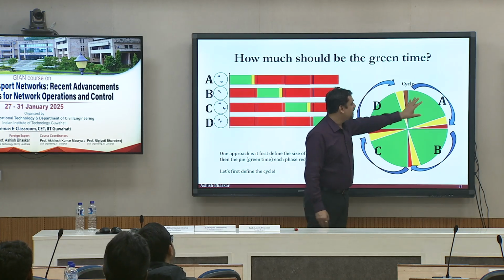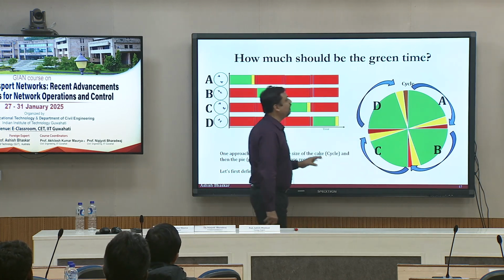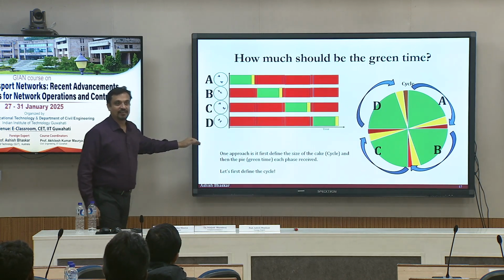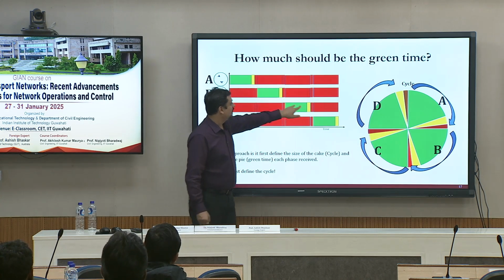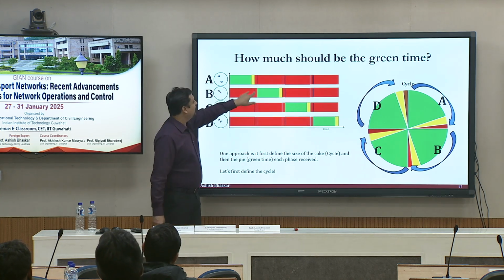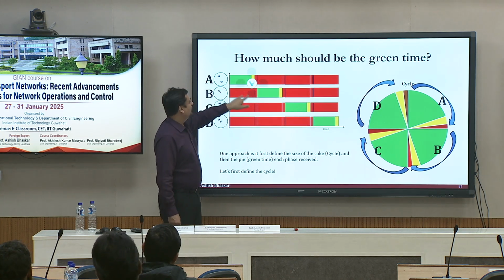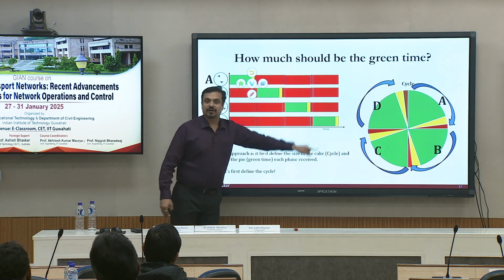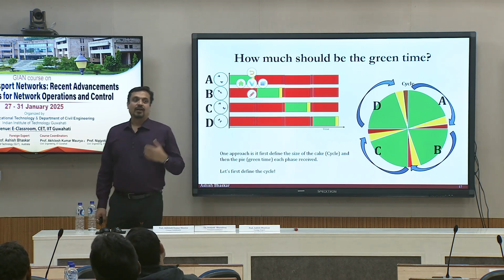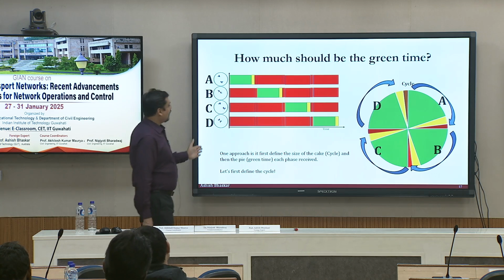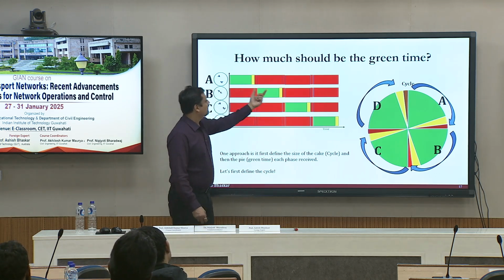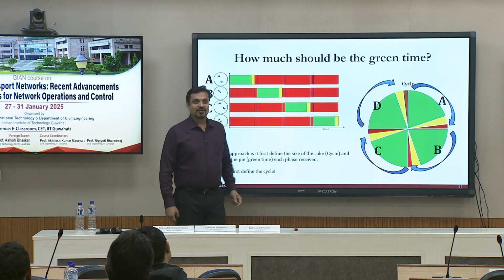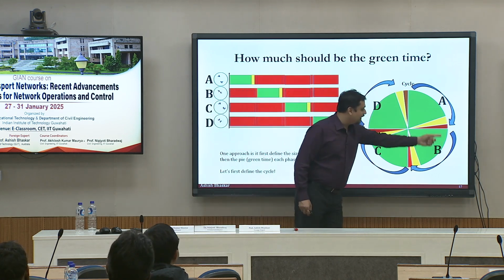The first step I have done was I defined my phases A, B, C, and D. Now let's call them A, B, C, and D for the sake of discussion. And I know these yellows and reds. When I'm going from A to B, that's the amount of yellow and red I will give. When I go from B to C, that's the amount, and so on. I have defined that. Now I have to define how long this cycle should be, and within that cycle, how much green should be.